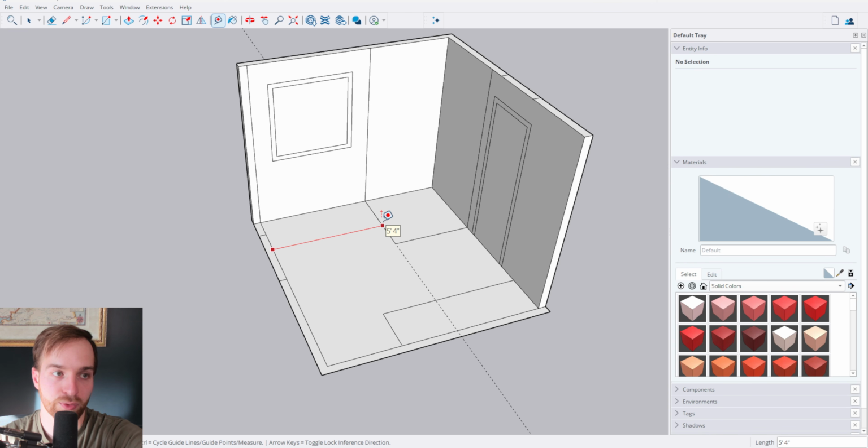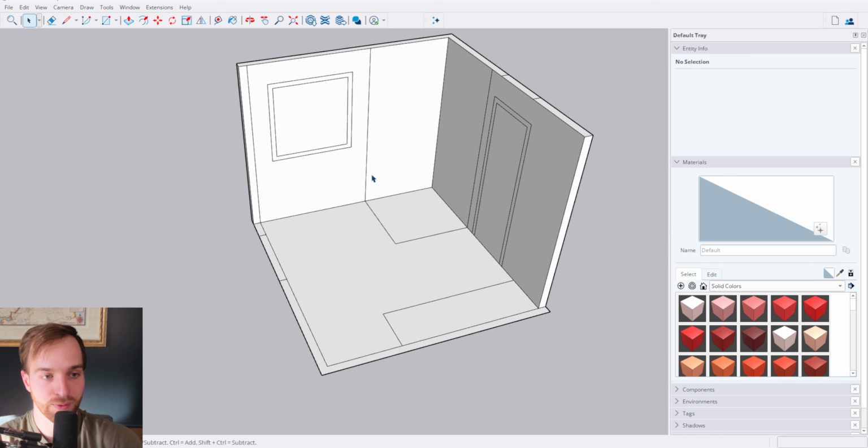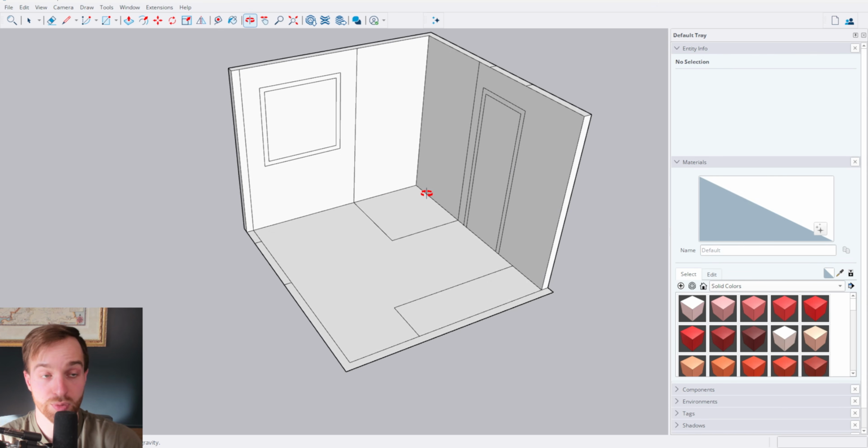So if they went for a tub that was going to be lengthwise like this, a standard 60-inch tub, it would leave a very small gap on either side, 2 inches. So a better option, and again, this is where the beauty of the model comes in, might be to consider a diagonal tub. But we do have our options. We're not going to get to that just yet. Instead, we're going to focus on a few other key tools within SketchUp.